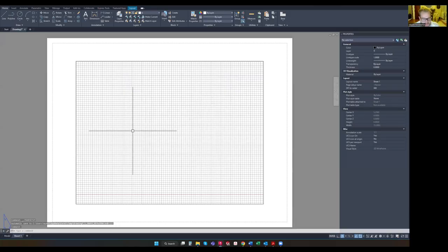Now, sometimes depending on how everything was set when it was installed, and it's nothing like your own fault, sometimes this little dotted line shows up. The white space you're seeing here is 8.5 by 11, this perfect white space. This little dotted line is the print margins. Depending on your computer settings and how AutoCAD is set, and I have never been able to figure out how to actually move these margins, mine is set at 1/4 of an inch.